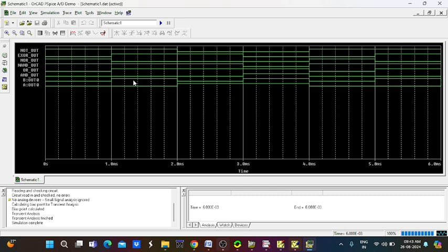That 0 is now inverted, your answer will be 1. So logic high is the NAND gate output. 0 plus 1 is 1. That output inverted goes 0. So the NOR output becomes 0 here. After that, XOR gate, when the two inputs are opposite, that is 0 and 1 condition, automatically your output goes high. And first my input A is equal to 0, so again the NOT gate output becomes 1.